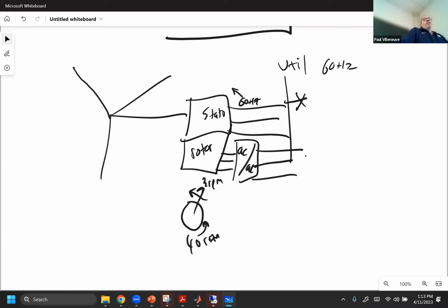And you can look at the terminology, and Nate, I don't know if this applies to you, but a lot of renewable energy equipment have requirements called low voltage ride through capability. So if the voltage goes poor, you have to be able to ride through, I can't remember the time, a certain period of time, and you can maintain the voltage so that the fault can be cleared and you can keep the wind turbine generation online.